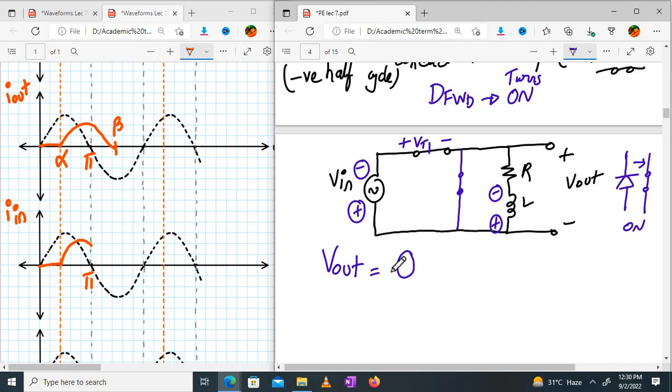No? Not understood. Did you understand how the freewheeling diode turns on? That much? So whenever a power diode is on, it is replaced as a short. And whenever it is short, the voltage across the diode might be 1 volt or 2 volt, that is very small compared to 325 volt. So that's why there is a short over here.